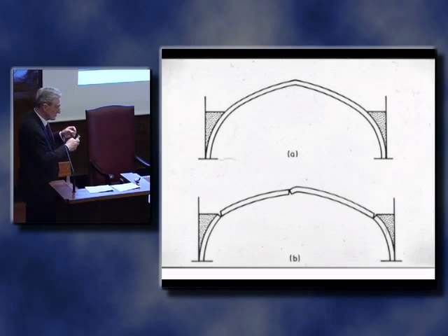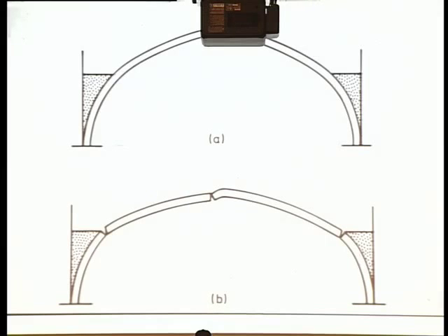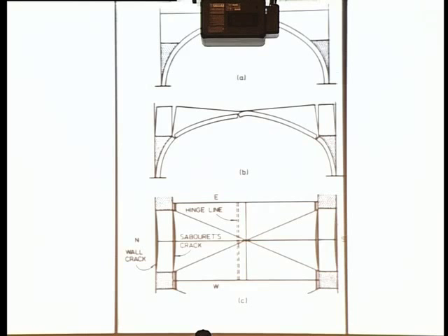The vault starts thrusting against the flying buttresses at this edge. The edges give way slightly, the span increases, and we get this cracking occurring, as we saw before with a simple arch. Now, let's go to the proper problem. That is the same cross-section here, but now with another vault running north-south, intersecting. We've got the same expansion, the same 3 cracks there. There's not enough material to fill this increased span for the vaults running east-west, the north-south vaults having expanded.